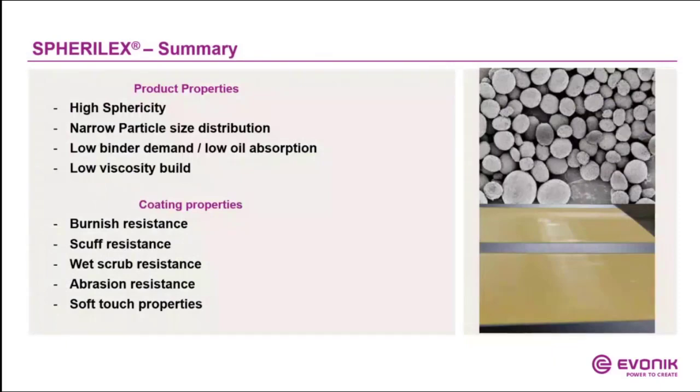To summarize this technology, SPHERILEX product properties: they have a very high sphericity. We can achieve a very narrow particle size distribution. The particles showed a very low binder demand or very low oil absorption number, and therefore they have a very low viscosity build in your formulation.